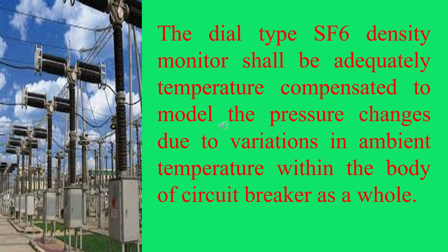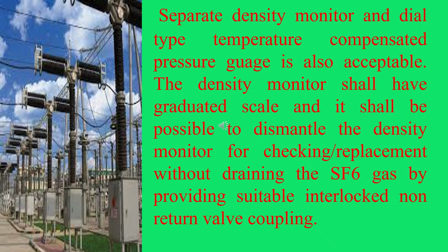The dial type SF6 gas density monitor shall be adequately temperature compensated to model the pressure changes due to variations in ambient temperature within the body of the circuit breaker as a whole. A separate density monitor and dial type temperature compensated pressure gauge is also acceptable.